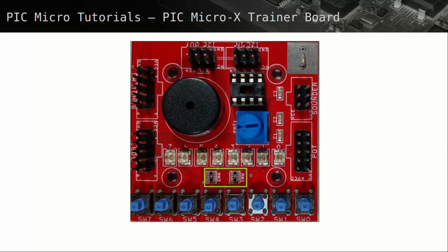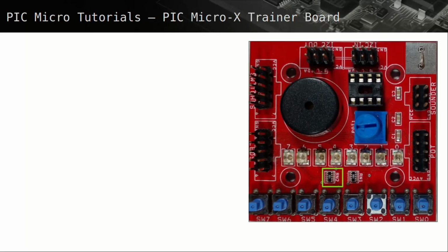Here are two resistor network components, RN1 and RN2, used with the switch and LED circuits. RN2 is used with the LED header. The number 102 for surface mount components has the first two digits value of 10, and the 2 is for the 2 extra zeros added, so 10 plus 2 zeros has a total resistor value of 1000 ohms.